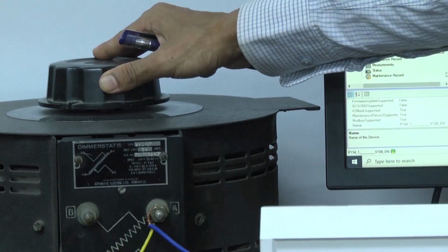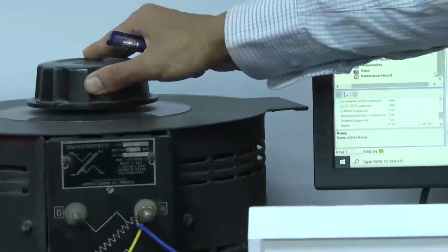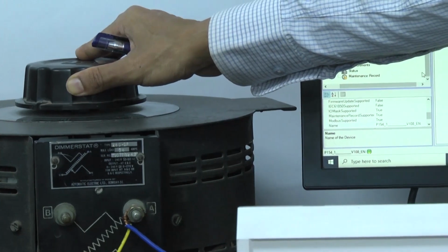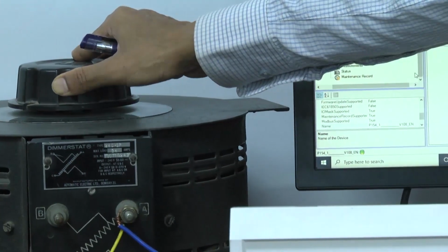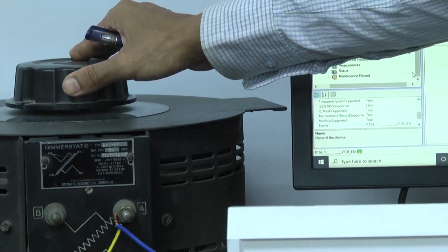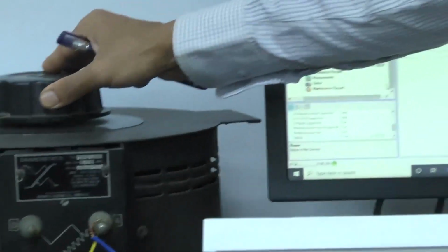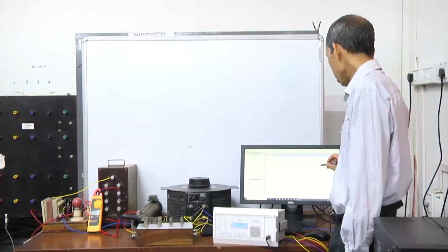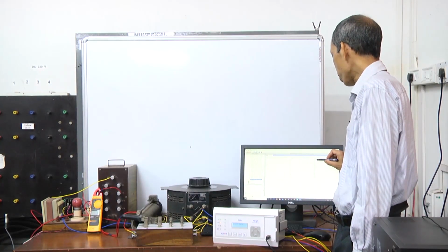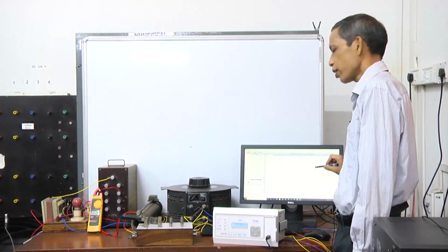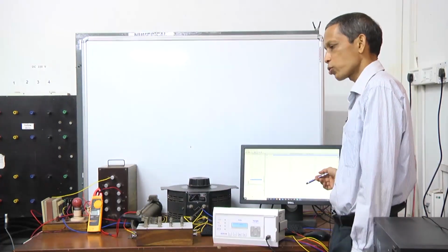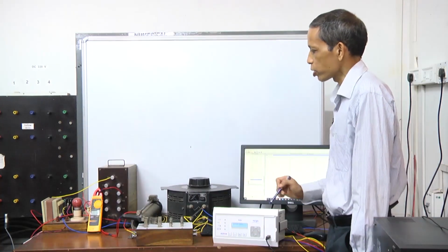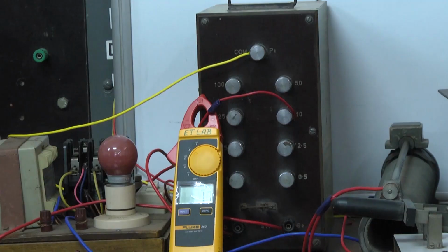So first we will go for the 2 ampere setting through this one, and then see the corresponding setting. Once you set the corresponding circuit to a particular current setting, the current showing here is almost 1.869, around 1.9 ampere, very close to 1.9 PSM. For this the circuit is closed now, and the relay is expected to function.